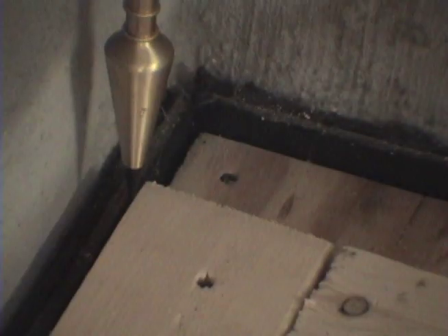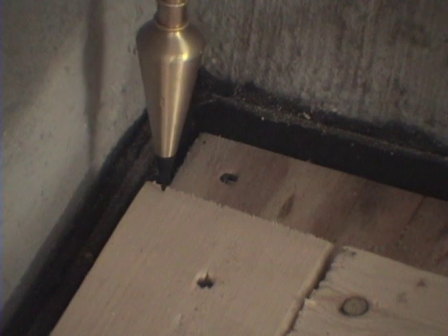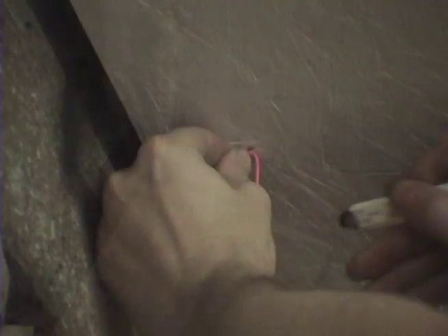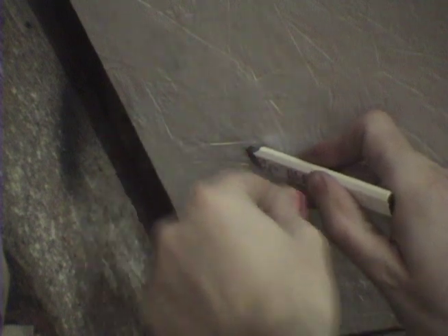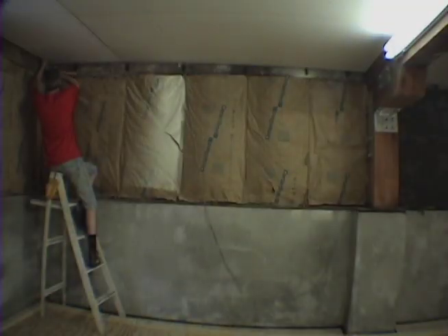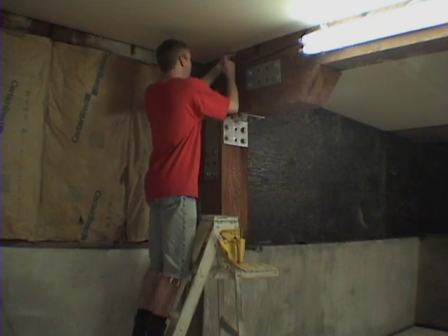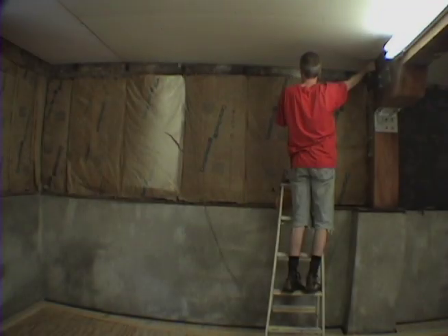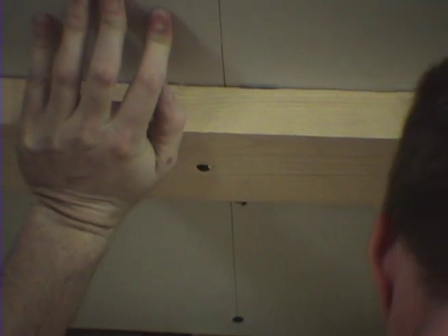The top plate will be the same as the bottom plate, same angles, same measurements, but to do this right, we use a plumb bob to find the corresponding point on the ceiling as it is to the floor. Place a small nail at that point, then find the corresponding point at the front wall. Snap a chalk line between the two, then you have a guide for the installation of the top plate. Pre-drill and mount 2 screws as we had done when building the ceiling, and run those in to hold the top plate in place. While referencing your RC markers, put the screws in on the RC channel and not into the ceiling beam.